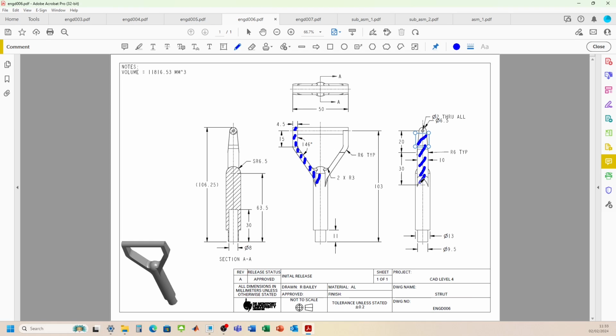So what you really need to do for this part is first of all focus on the side profile. So you draw out the side profile. Everything's been given to you for the side profile, and then you can draw out the outline of that side profile, and then you need to extrude it out 25. That will give you a solid block effectively that's covering this area here. It'll be a rectangle, but with this side profile.